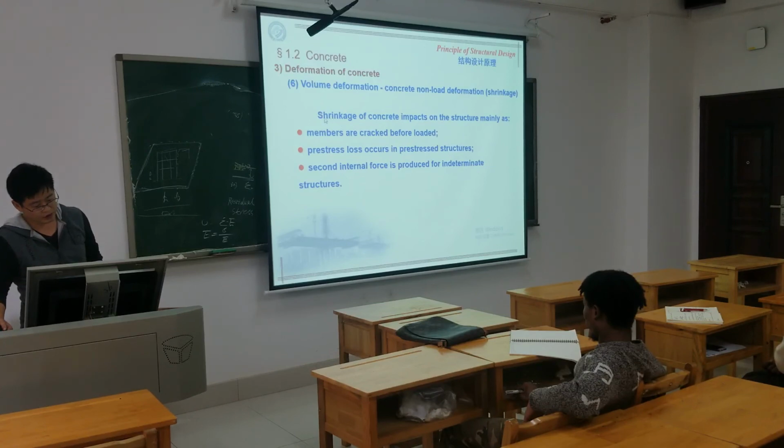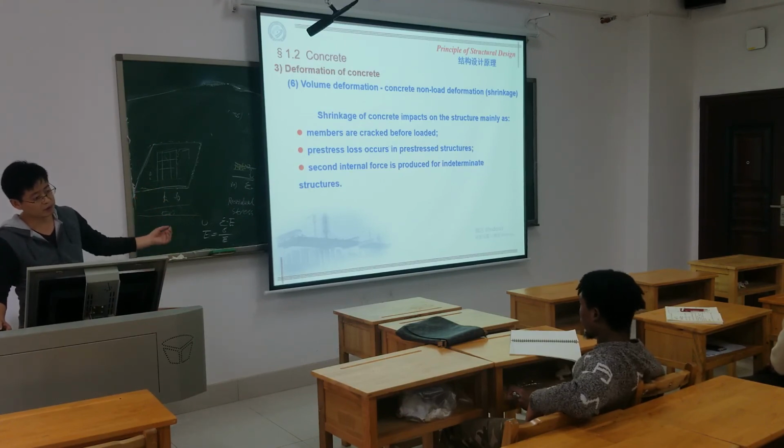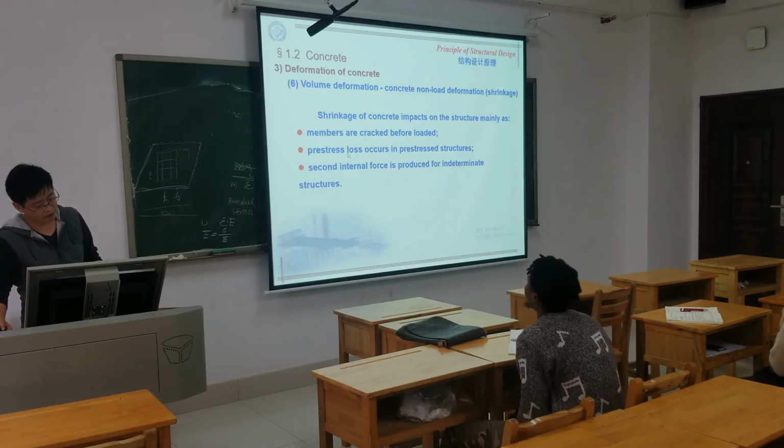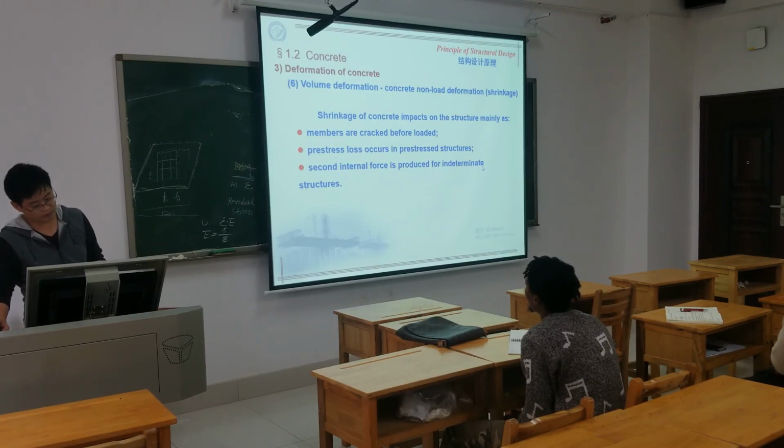The shrinkage of the concrete impacts the structure mainly as member cracks before loading. Before putting it into use, maybe with no load outside on the structure or component, it's already cracked by itself. It also induces pre-stress loss. And secondly, internal force is produced, the same as creep.